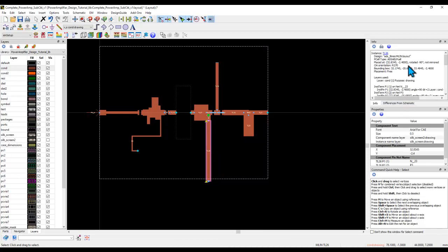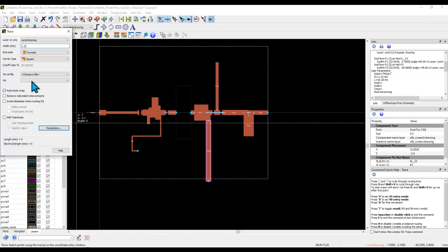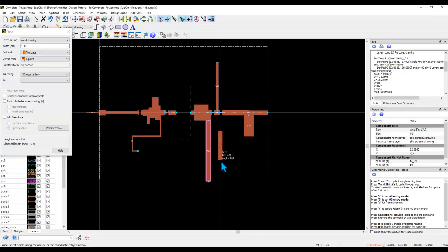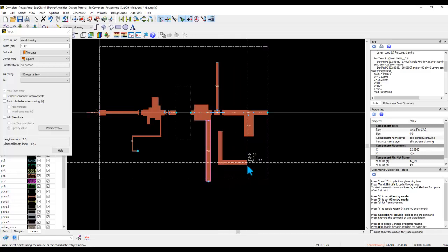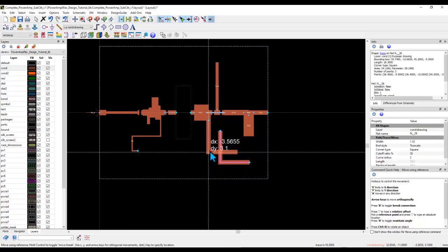Now this line, which I wanted to convert, is 1.32 mm in width and 18.3 mm in length. So very quickly, we can go here, change it to 1.32 mm, corner square, truncate, and I can start drawing some line of around 9 mm or 10 mm approximately, whatever you prefer. And then we will go to 18.3 mm and simply draw that line. Remove this line and connect this.